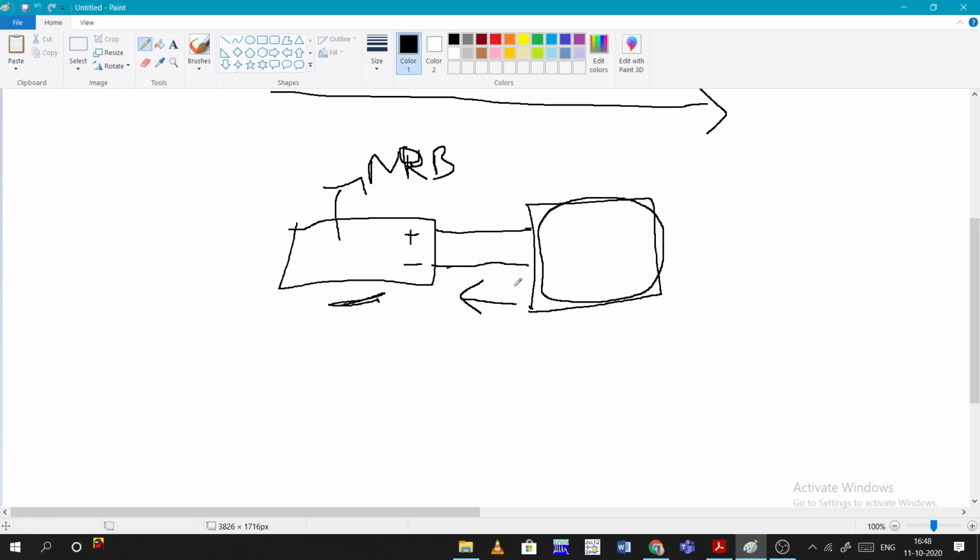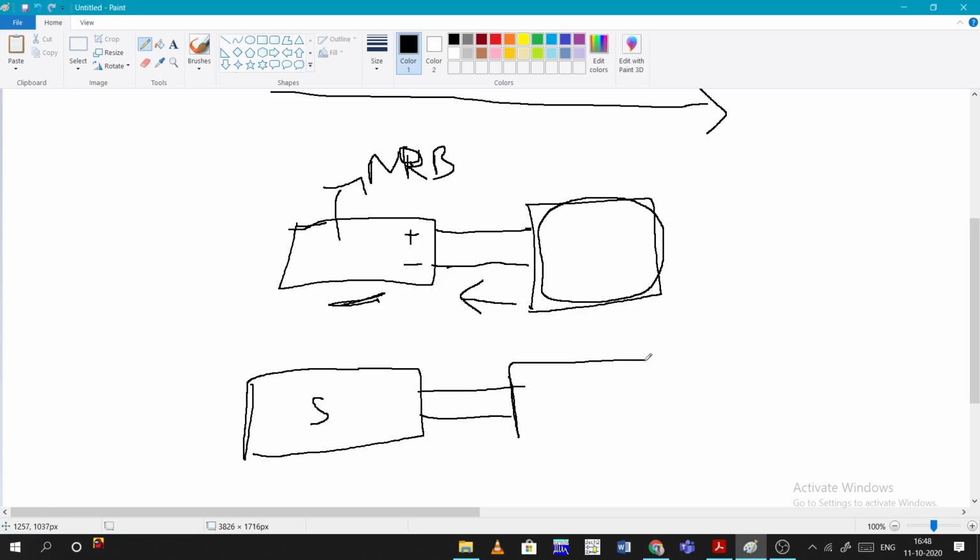Since these are very high frequencies that you are using in microwaves and radios, that will definitely damage the EM source. So to avoid this type of damage, what we will do, if the source is a microwave source, is immediately connect an isolator to it.